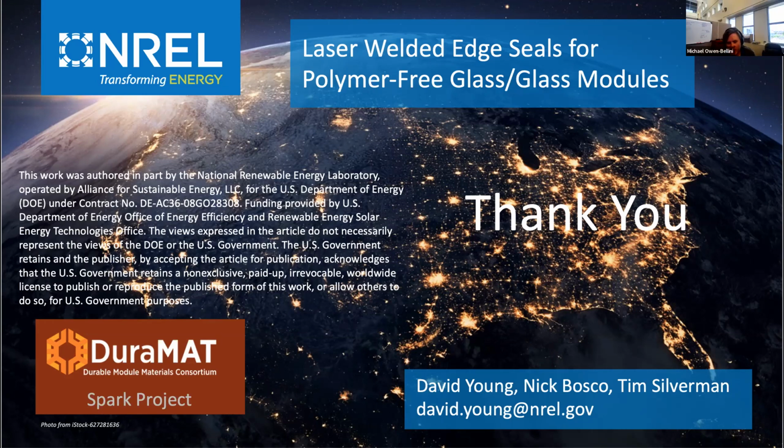In the case where you are relying on the ribbons to hold down the cells, and perhaps this is a question for Nick, who's also on the call, do you think that could have additional implications for the stress applied to the solder joints, and could you have additional issues with solder joints in that situation? Yeah, that's a great question. Traditionally the encapsulant definitely constrains the cells, and sometimes that's good or bad in terms of thermomechanical fatigue of the solder